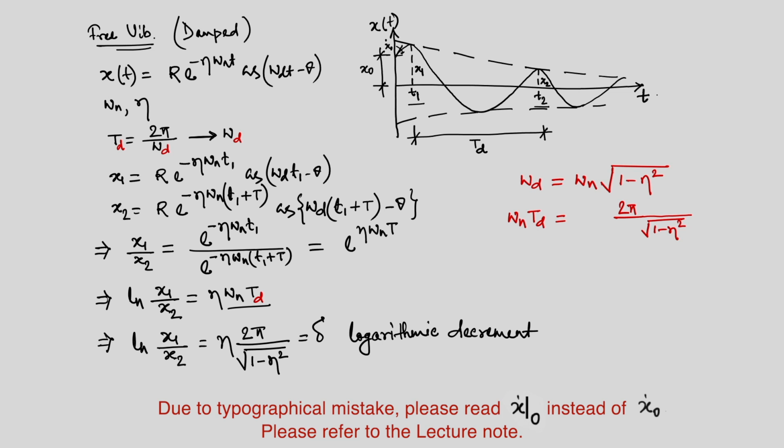So, as time progresses, obviously the response reduces because of the presence of damping. Now, if we look at this response quantity and we can measure it, then from that first we can identify this damped time period, and from there we can find out the damped natural frequency.